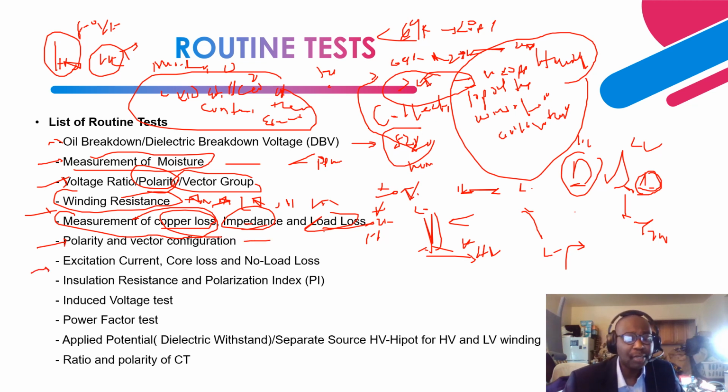Okay, so this is the no load loss test, right? For this one, they call it the open circuit test, right? Where basically, you have the transformer over here. You have a measuring ammeter, a voltmeter, and then a wattmeter, right? The wattmeter is in phase A, phase B. The low voltage side is open circuited, right? It's open circuited.